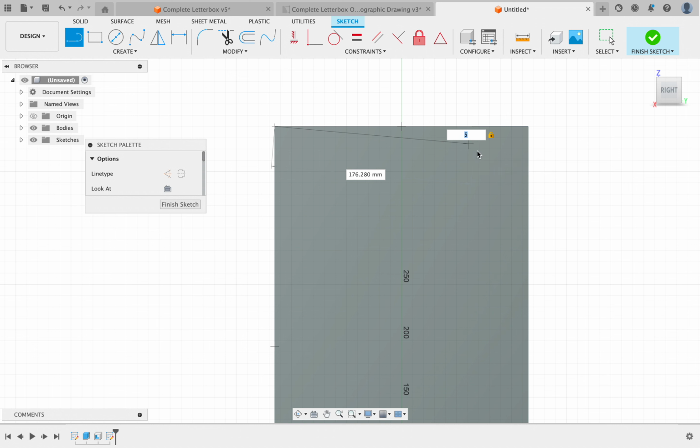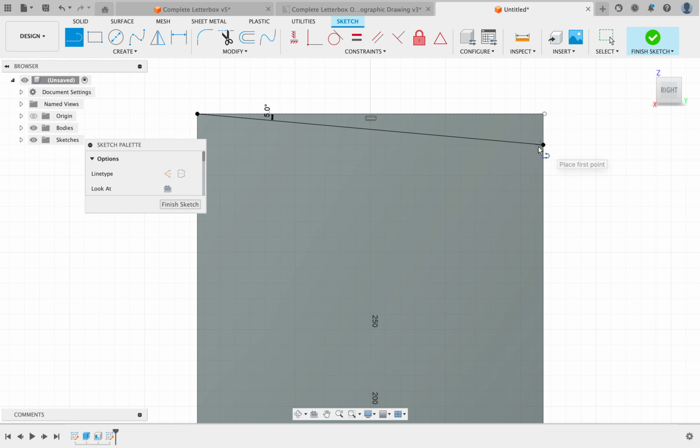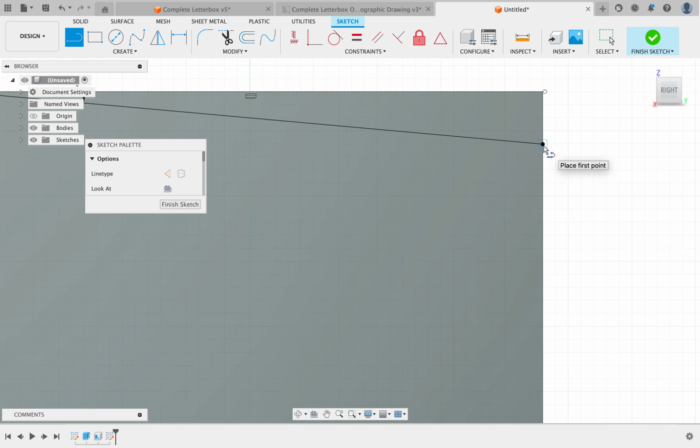Now, because it's a wee bit of a complicated maths equation and quite a small number, I'm going to let Fusion 360 do the maths around finding that exact length across that span. So you can see there, if I just let the cursor do the work, I'll get this small blue cross here, which tells me that it's intersecting with the body of the shape that we've made. And we can now see that that line is going right to that edge. It's less than a millimeter difference across that span.